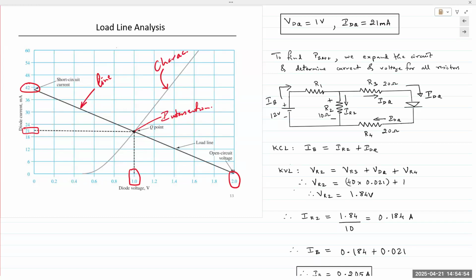So as practice, you can plug in Vs equal to 5, 10, 15, or 20 volts. You have all the equations. All you need to do is crunch the numbers. So you plug in the values in the equation, you obtain the Thevenin voltage, Thevenin resistance. Resistance stays the same because that's not changing.